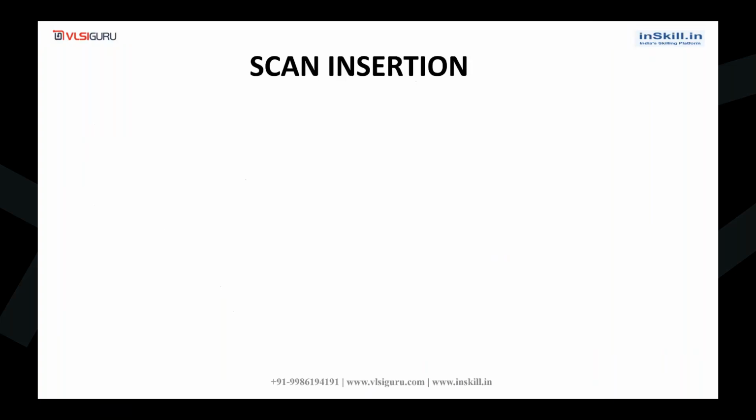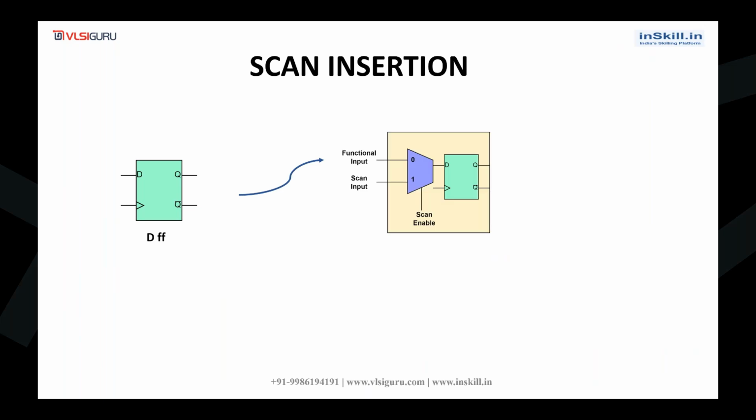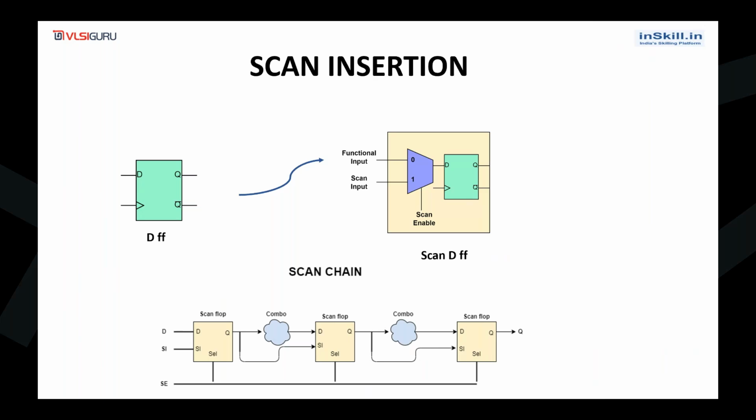The first one is scan insertion. Scan insertion means all the normal flops in the design will be converted to scan flops, and these scan flops will be stitched into a scan chain.